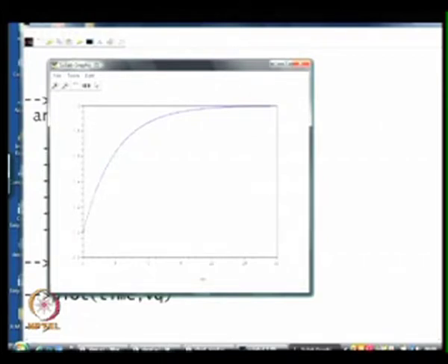Approximately 5 times the time constant is the settling time. So, this e raised to minus t by Td0 dash is very clearly visible as a slowly, exponentially rising response in Vq.